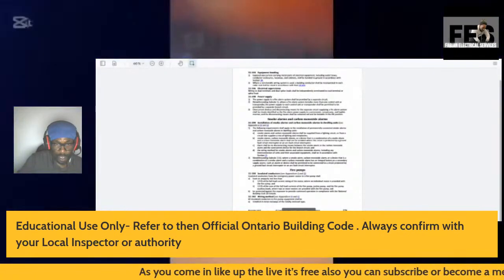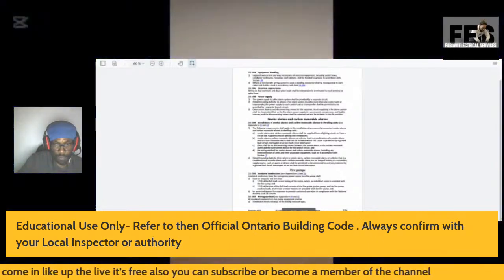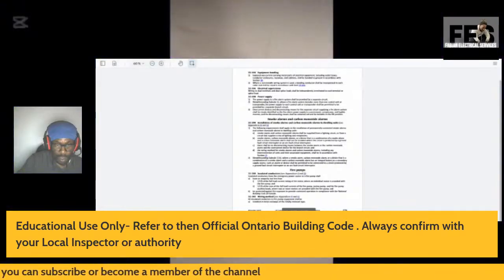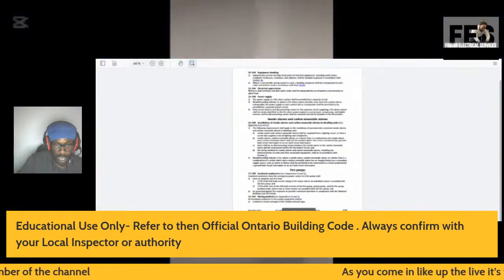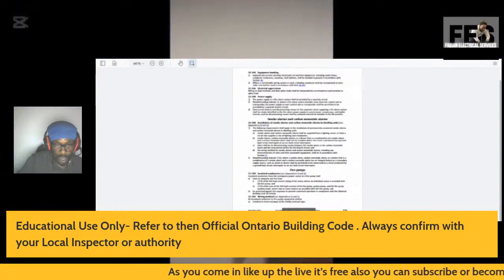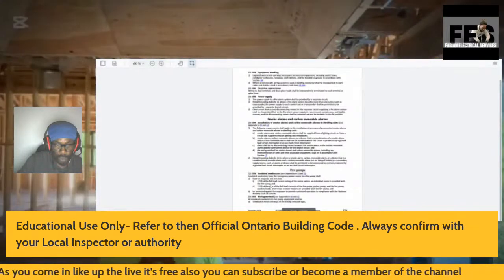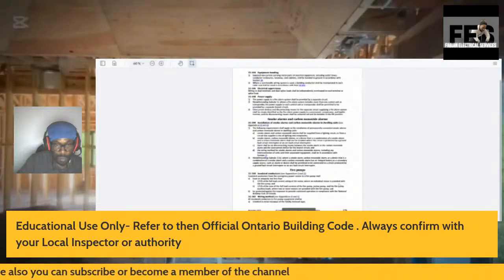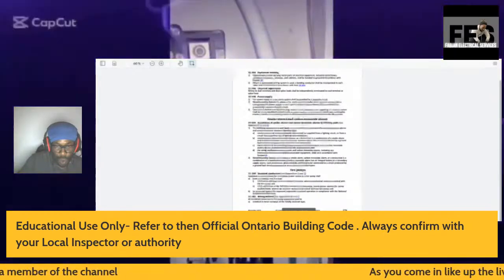Insulated conductors from the emergency power source to a fire pump shall have an ampacity not less than 125% of the full load current rating of the motor, plus 25% for auxiliary loads, where two or more motors are connected to the